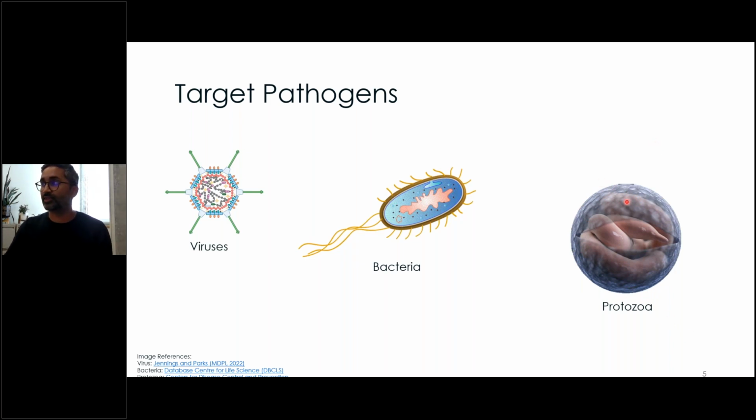So in order for chlorine to get through and disinfect protozoa, one thing you'll see if you look at the guidelines is that the CT that's required for protozoa would be a lot higher than it is for bacteria and viruses. So we'll look at some of those numbers and we'll get into what it means to have a higher CT.